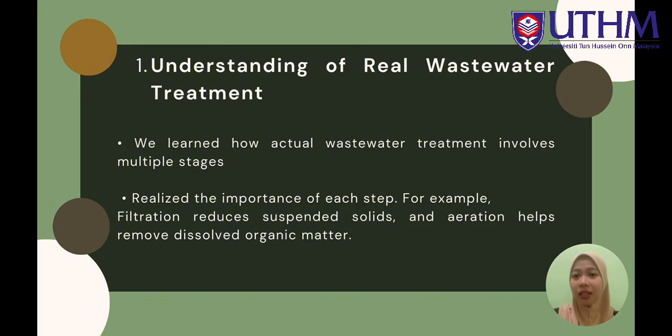Experiment, the insight is the understanding of real wastewater treatment. Learn how treated wastewater treatment involves multiple stages, which are filtration, pH adjustment, equalization, and aeration. Realize the importance of each step. For example, filtration reduces suspended solids, and aeration helps remove dissolved organic matter.